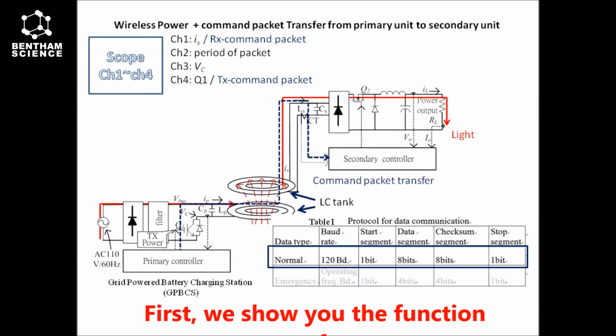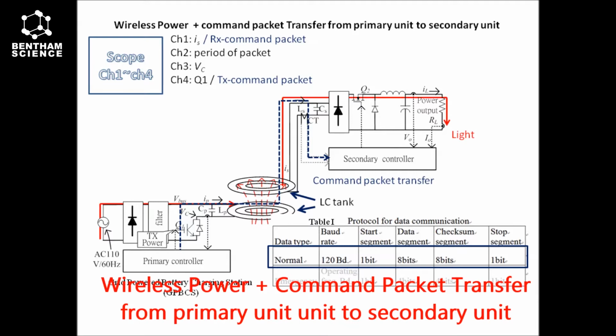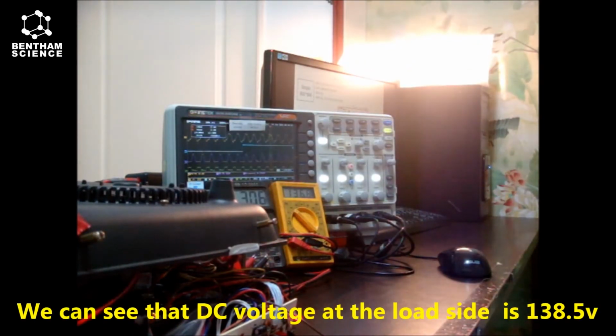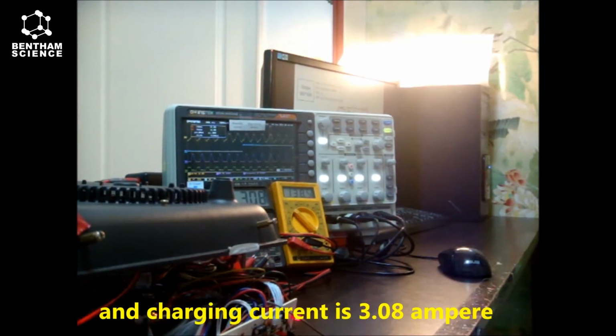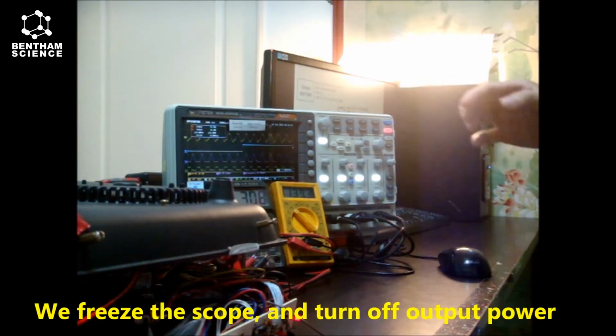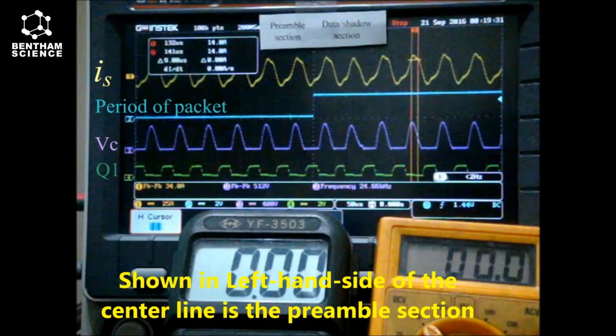Let's start the experiment. First, we show you the function of wireless power plus command packet transfer from the primary unit to the secondary unit. Let's start power transfer. We can see that the DC voltage at the load side is 140.5 volts, and the charging current is 3.08 amperes. We freeze the scope and turn off the output power.